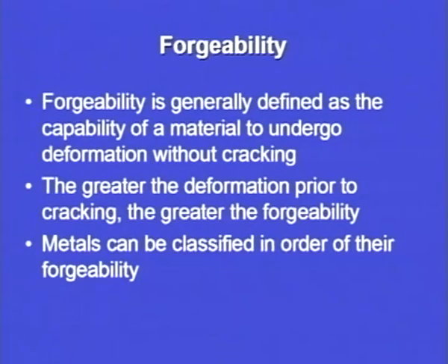So, what is the limiting factor? The limiting factor is the cracking. As soon as cracks start to appear on the material, we say that this is the limit up to which this material can be forged. Every material will have certain forgeability and certain limits up to which it can be worked using the principle of forging.